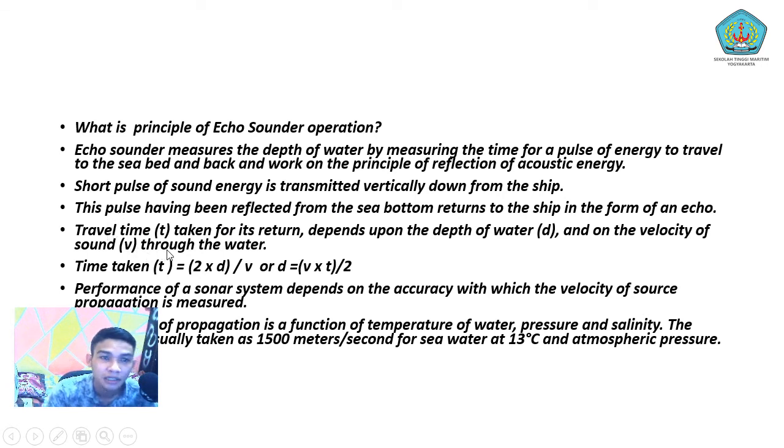Travel time, called T, taken for its return, depends upon the depth of water, called D, and on the velocity of sound, called V, through the water. Time taken T equals 2D over V, or D equals V times T divided by 2.